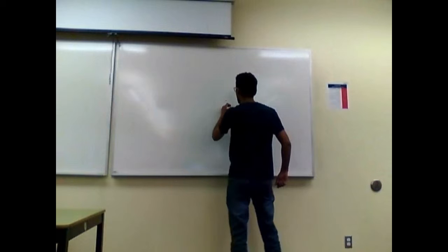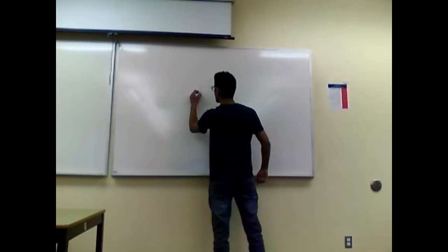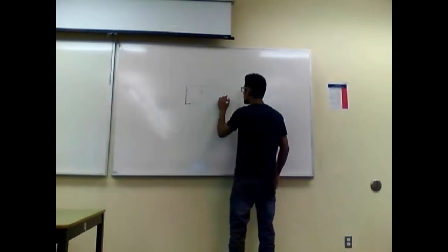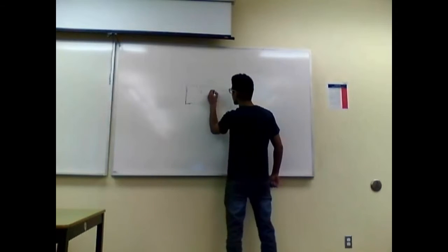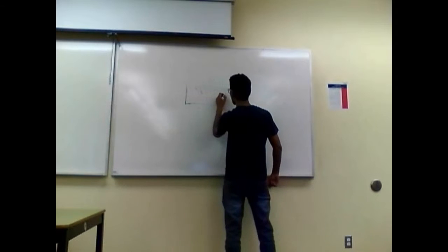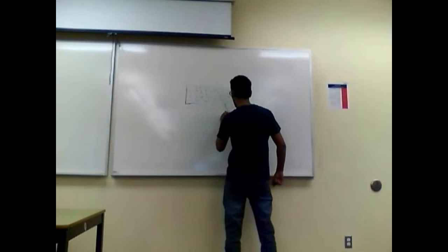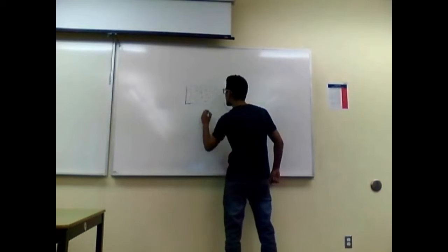As you can see, this is the material. It is actually a magnetic material, so we can only perform this test on magnetic material. This is the crack, and we have to detect this crack. When we connect it to the electricity, the magnetic flux lines flow. They are longitudinal in this case. So these are magnetic flux lines. And this is the crack.